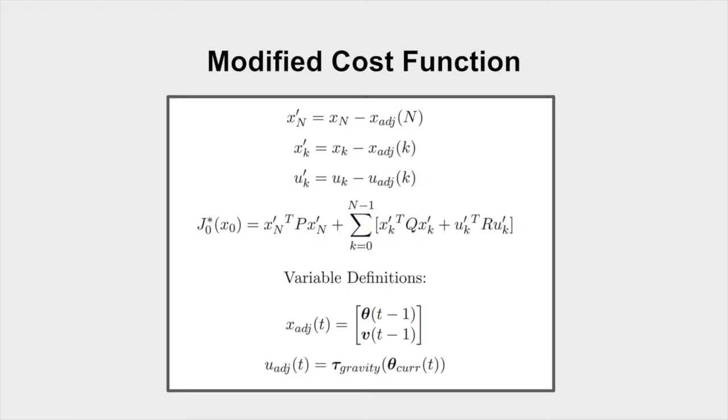Like on the midterm, the position costs were zeroed around the current point in the pre-computed trajectory we wanted the end effector of the arm to follow. We allowed the arm to switch the target trajectory point after the Cartesian distance to the current point was below a certain epsilon value, so it would not have to spend time converging exactly to each individual target.